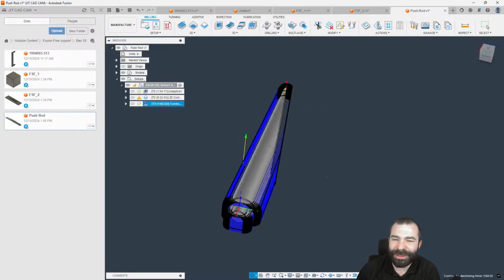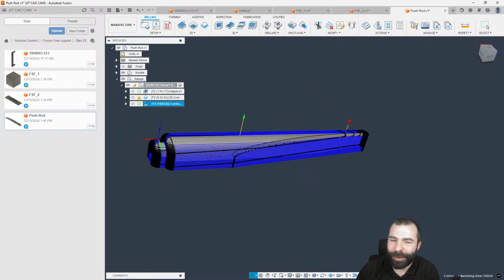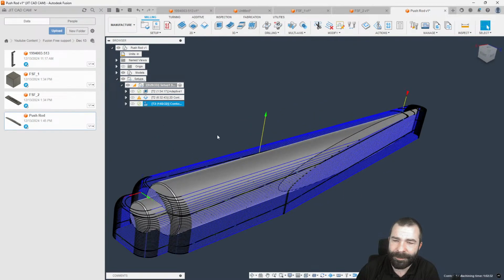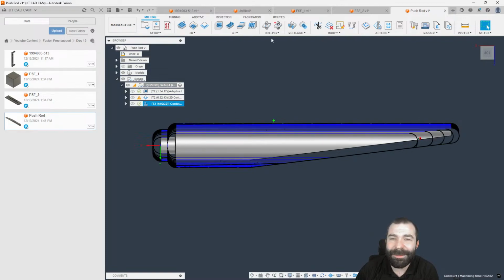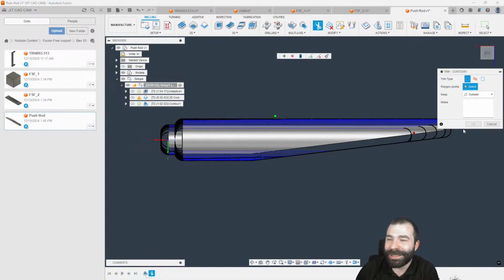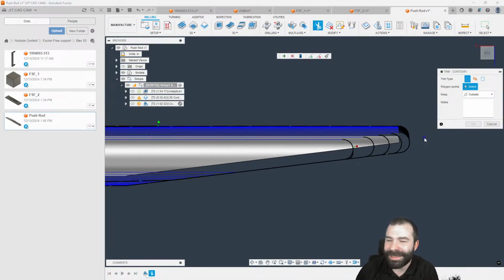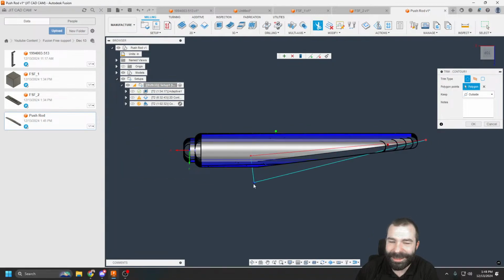And I'm going to make sure I get a toolpath on my part before I really start messing with anything, right? So one thing in the world of Fusion, if you paid for the extra features, we could actually cheat. And I mean cheat because I could go in and trim toolpath and say, you know what? I only want to keep everything in this area.